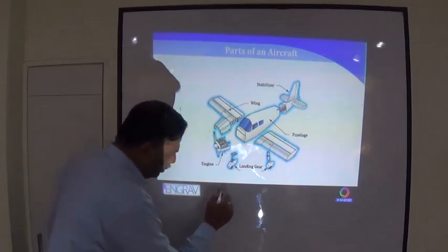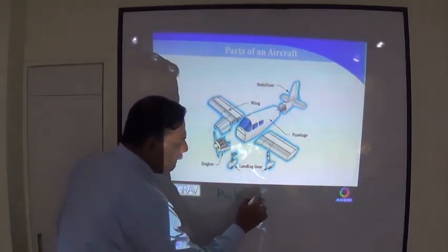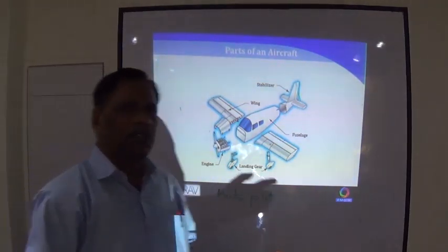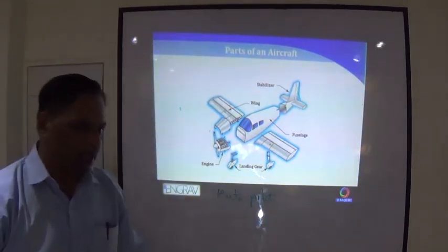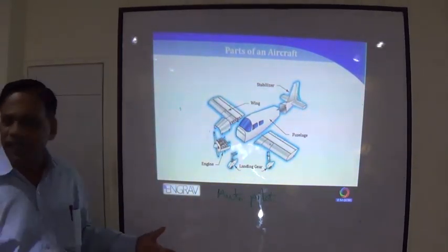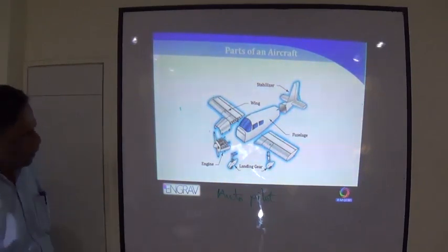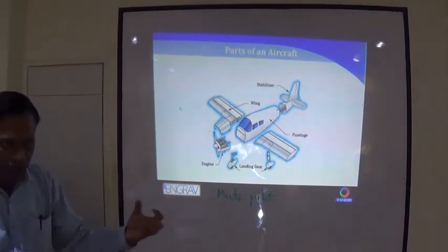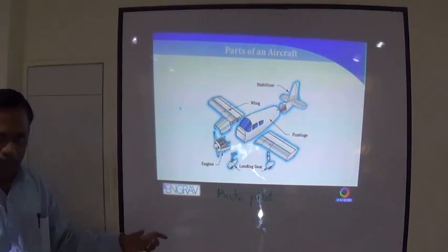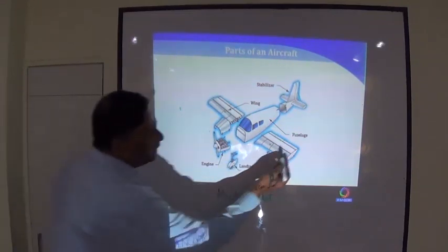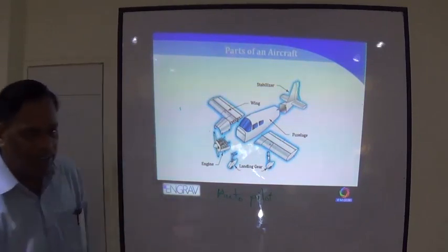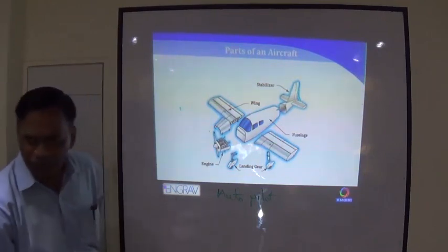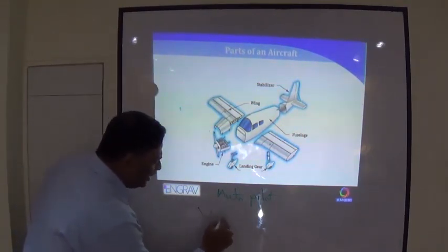Aircraft, and ships also, have something called autopilot. So after takeoff and climb, once you are around 3,000, 4,000 feet, you engage your autopilot. Then the autopilot system takes care of the aircraft. What the autopilot system does is it has sensors to sense the aircraft attitude, whether it is left or right. The sensors are generally, I'm sorry I'm using a little more jargon, but interesting I suppose, the VG, vertical gyro.